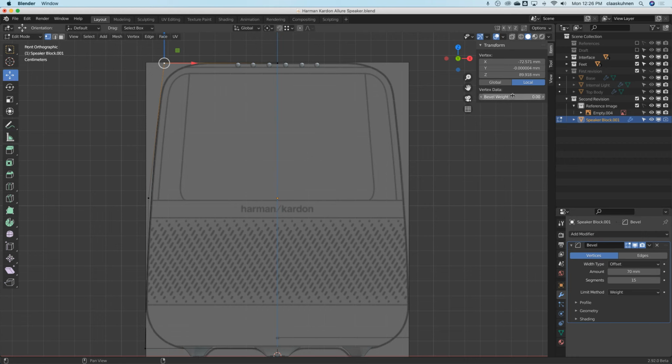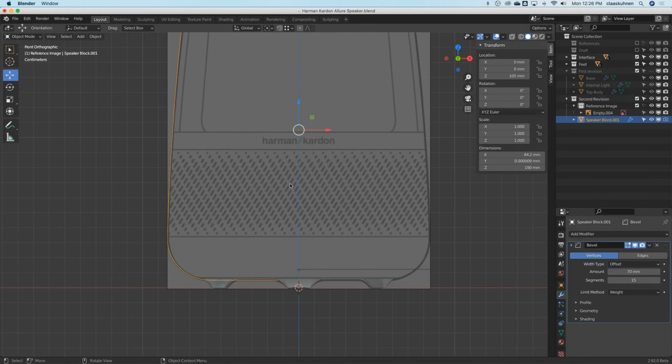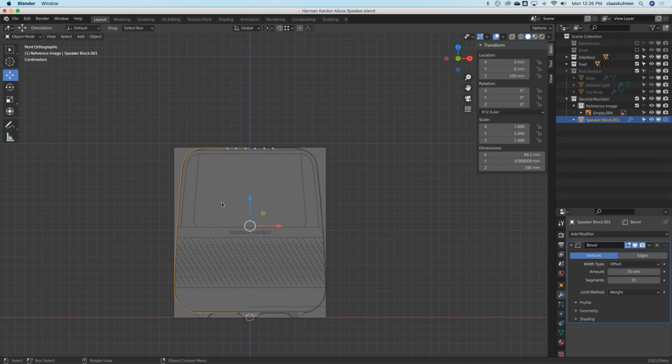And then we can go to here, and now there we just have to be careful that we can't go 100% because then we start cutting into the previous fillet, maybe a little bit smaller. So we work just with the percentage. And that's actually as you see so far, it's actually quite easy to do.